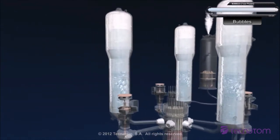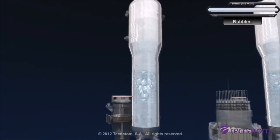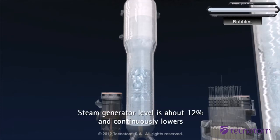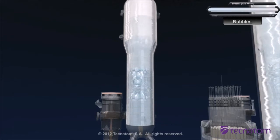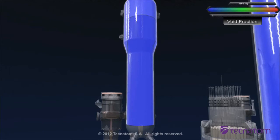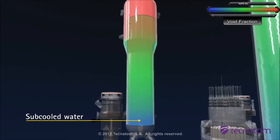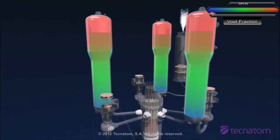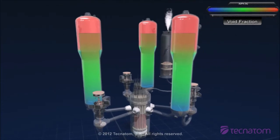At the same time, steam generators are going dry as a consequence of a complete loss of feedwater. Auxiliary feedwater failed to actuate after the main feedwater pumps tripped, and steam generators can no longer be considered as a valid heatsink. Changing to a void fraction representation of the steam generator, subcooled water is represented in blue, and steam is represented in red. We can clearly notice the amount of subcooled water in the steam generators.